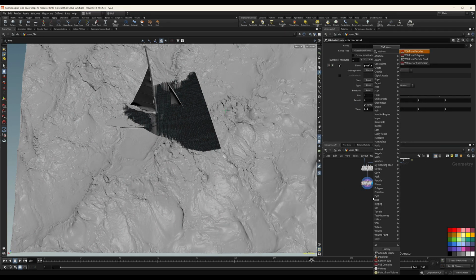And also I thought it was important to get the key concepts of flip simulation doing the traditional way, without the new nodes of 19.5, because sometimes you work in studios, and some studios don't change for new releases of Houdini because the project's already running, and you don't want to have different issues because you updated your software. So they tend to keep using a previous version for a long time. Some versions are really solid, and they already have their own plugin for that version, so that's also important.